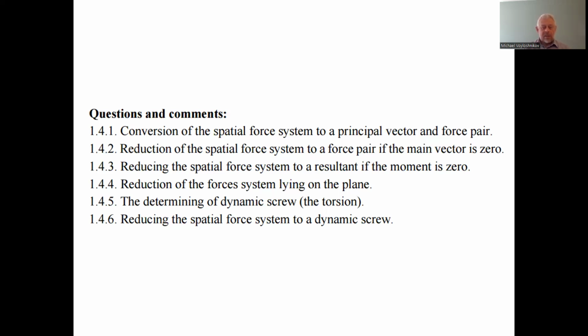We decompose the main moment in the manner that in the couple of forces, one of the forces in the pair and the second one are of the same magnitude as the main force, and as the moment is a free vector, we make the point of application of one of the forces of the pair coincide with the point of application of the assigned resultant acting on the mechanical system, and acting opposite to the assigned resultant.